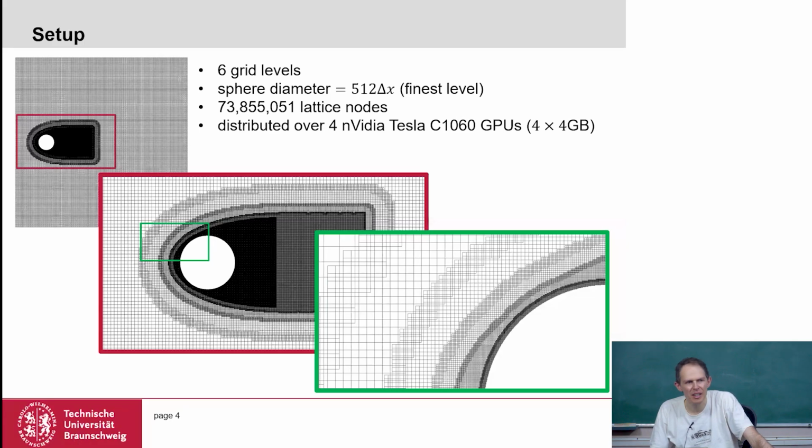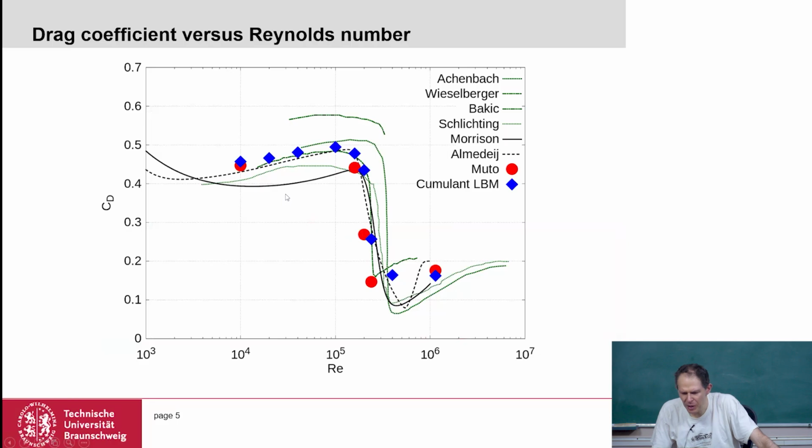So Cartesian grid method means we cannot easily use a very fine grid at the boundary layer. Of course we can refine the grid, but other than in OpenFOAM, where you have these boundary elements with very high resolution directly on the boundary, this is difficult to do with a Cartesian grid method, because changing the resolution is not straightforward. Therefore this particular behavior that we observe in the flow around the sphere was very difficult to capture with the Lattice-Boltzmann method, and required special attention.